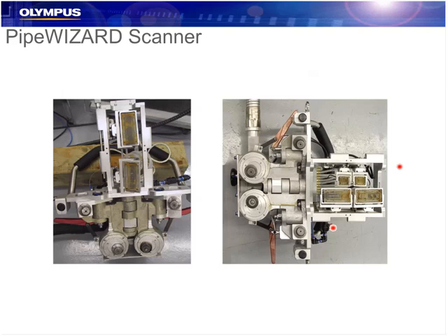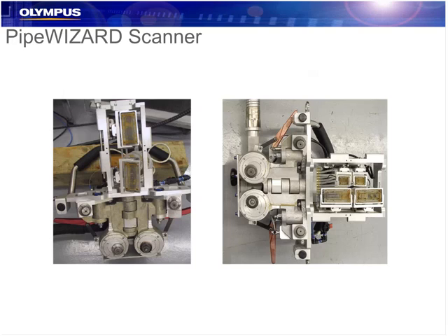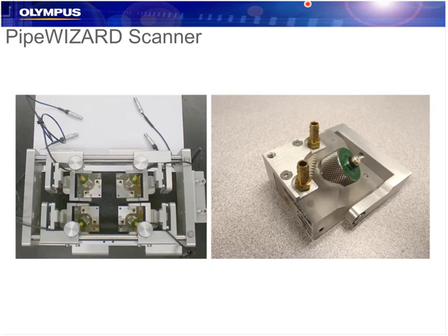Often we'll use a larger carriage and we can add time of flight diffraction. And other slides will also show some other adaptation for other ultrasonic needs. So here we look at a transverse module. So if I go back just one slide, here is a connection. We'll be able to connect another module onto the unit, expanding the footprint of it. And now if we need to shoot across the weld, we often use just conventional ultrasonic transducers to look for things like transverse cracking or transverse defects if there's a requirement for that. So it is adaptable to different ultrasonic techniques.